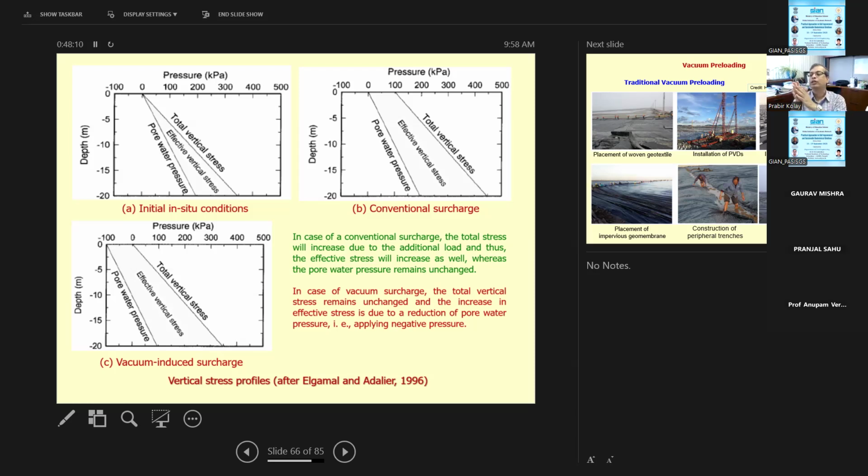More cohesion. So now, pore pressure increase means what? Assume there is a soil particle and another soil particle. The pore pressure is the water filling the voids in the pore space, right? So pore pressure increase means the water pressure will try to separate these particles. Instead of friction increasing the strength, it separates the particles, so suddenly the soil loses its strength. That's why during an earthquake, the pore pressure increases, the soil suddenly loses its strength because there is no contact between the soil particles, and then the soil collapses, or the foundation collapses.